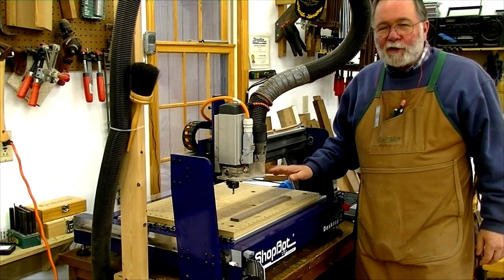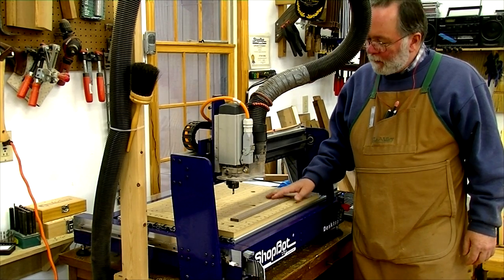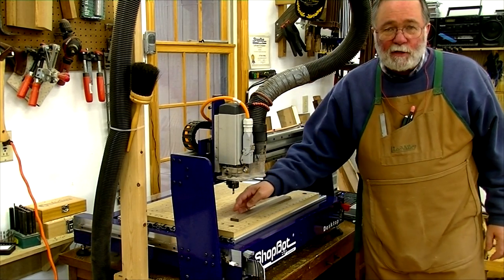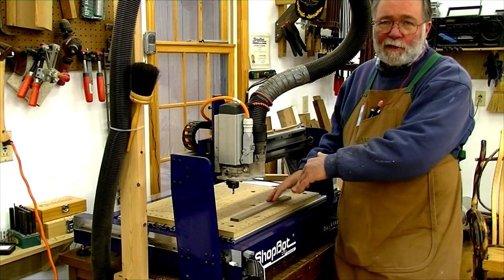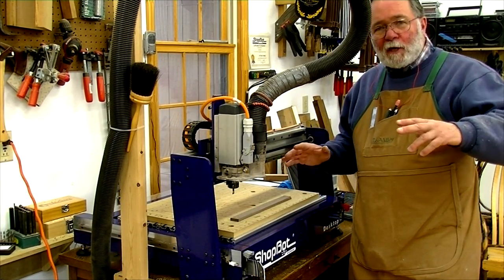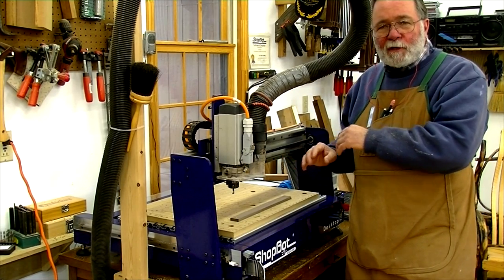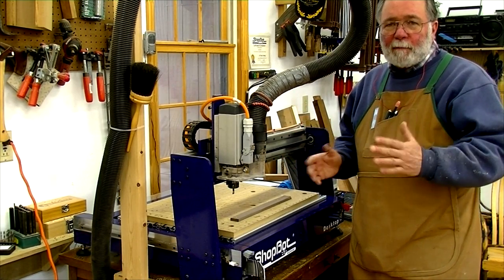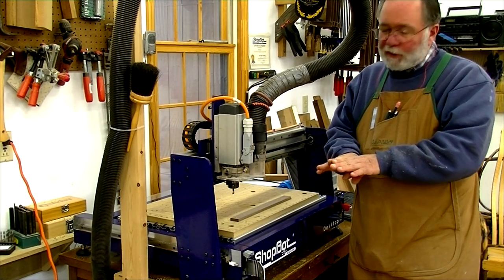Before I start actually cutting the material for the pedestal, I want to have a nice fence on which to align the material, because it's important that the cuts are nice and square so that each end has the same dimensions, and when I miter them together, everything will mate up.